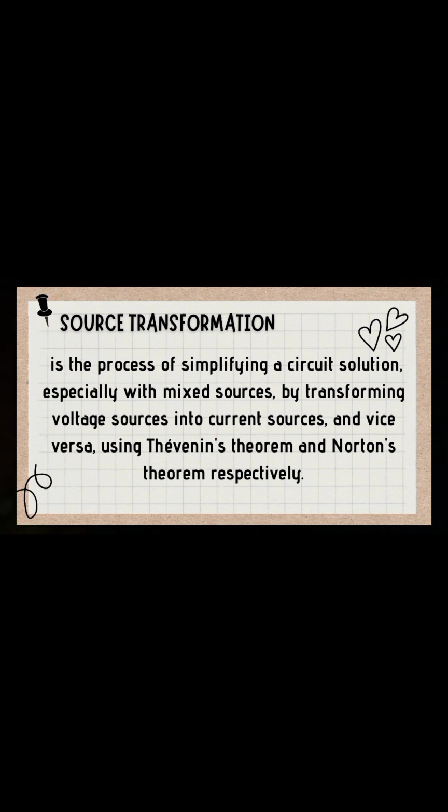Source transformation is the process of simplifying a circuit solution, especially with mixed sources, by transforming the voltage sources into current sources, and vice versa, using Thevenin's theorem and Norton's theorem respectively. Also, source transformations are not limited to resistive circuits. They can be performed on a circuit involving capacitors and inductors as well, by expressing circuit elements as impedances and sources in the frequency domain.